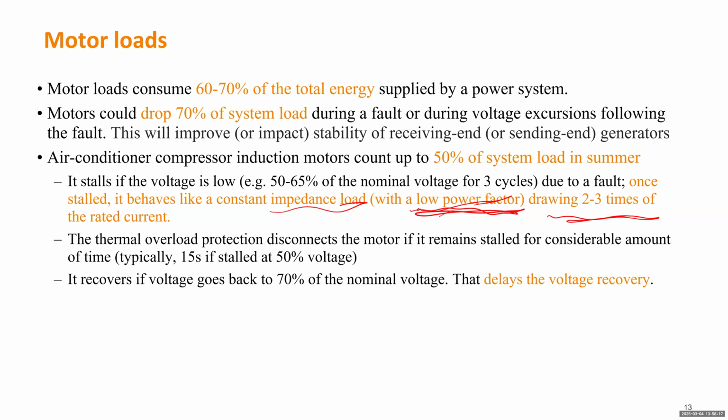Then after the fault is cleared, when the voltage recovers, the induction motor will think, okay, I need to go back. So they will restart. But restarting an induction motor also needs a lot of reactive power. The worst case will be some induction motors will keep restarting for a long time, which will consume a lot of reactive power after the fault. That time can last maybe 30 seconds.